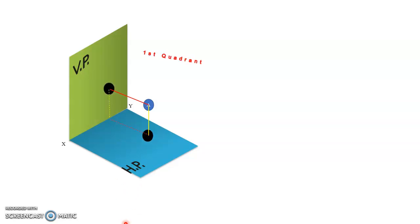The front view and top view are given here. The front view is 20 mm above the XY line, and the top view, seen from the top, is 30 mm in front of VP, so it comes below the XY line when we tilt the HP.